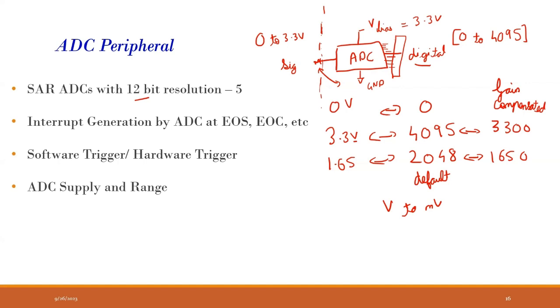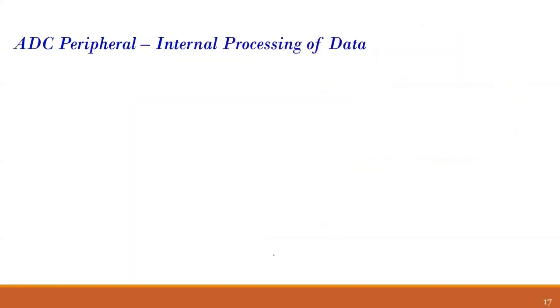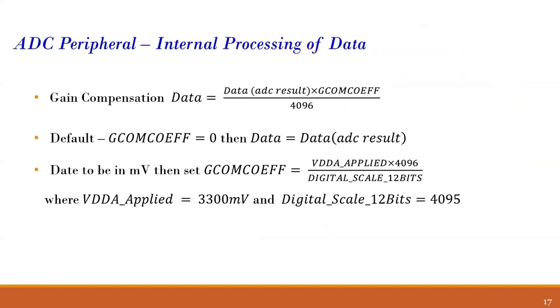Okay, sir, can proceed. Another thing is my ADC needs a clock, a trigger clock. Only then it will start sampling. When it gets a trigger, it will take the sample, and then it will give my digital output, the digital data vector. This trigger signal I have to generate. How do we generate these trigger signals? That I will show. Okay, this is for gain compensation.